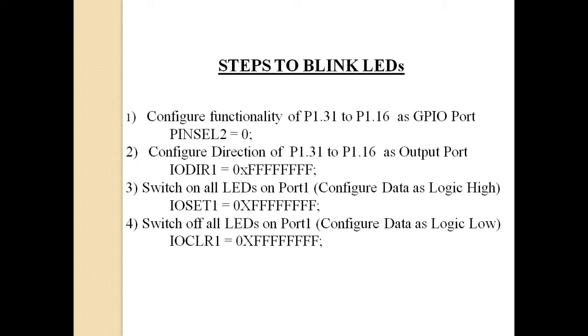The second parameter you need to configure is the data of those pins. So data means what? Say in my case you are connecting an LED, so you are configuring the direction as output. Then I need to make the LED on. How will you make the LED on? In that pin you need to write a logic high signal. So logic high means VCC or the supply voltage of this controller will be generated in that pin.